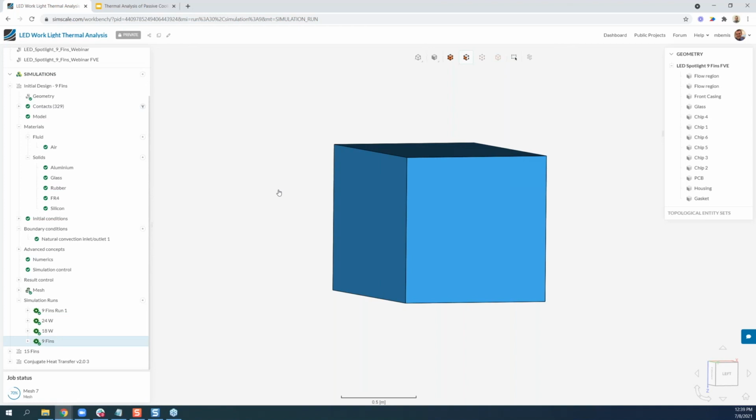Hi, can we evaluate the U value in the construction industry? Sure. The answer there is yes. So what you're going to end up having is an assembly of a wall with your different materials, for instance drywall, and then insulation, probably some wood studs. You could import that assembly. I've done it with Revit, and you can assign a temperature delta across it and figure out how much heat transfer you have going through, and back calculate a U value.